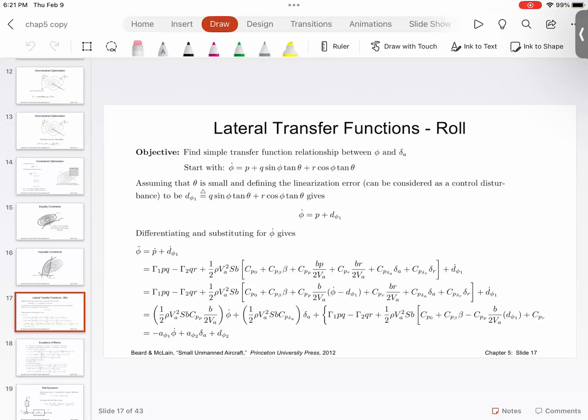First and foremost, the equation is nonlinear. A transfer function does not exist for a nonlinear system or nonlinear dynamics. Remember this. The equations that we are dealing with are nonlinear. They are coupled. So in a true sense, the transfer function does not work. So what are we going to do? First, we are going to look at that nonlinear function, then approximate it to the best of our judgment. And after approximation, the things that we cannot cancel, we are going to treat as disturbance.